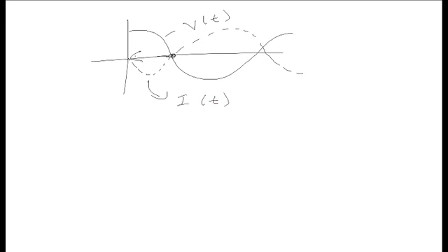What this means is that V and I are referred to as out of phase. In this case, by 90 degrees. Lagging. In a capacitor, you can do the same analysis, and you'll find that the current leads by 90 degrees.